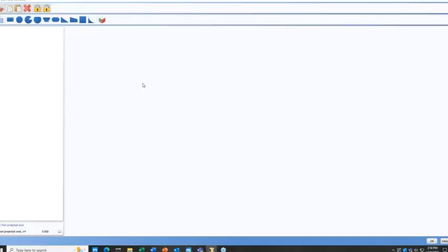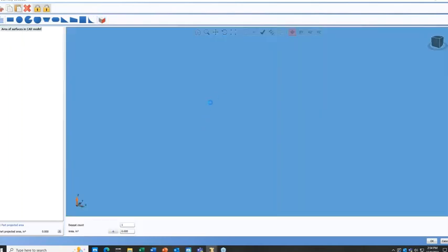So we're going to complete this dynamic costing analysis. This basic data, we're going to accept all of that. The part volume and part weight have been brought in from my CAD model. Here is a difference: our part projected area for the last part was not classified as an important input. In this case, it is. So we're going to define it, and I'm going to define this information using the CAD model.